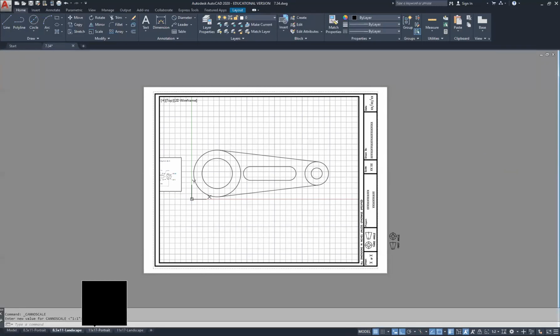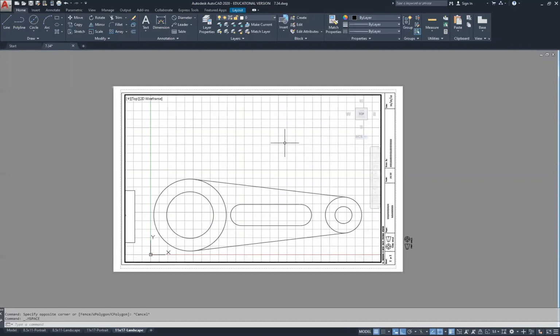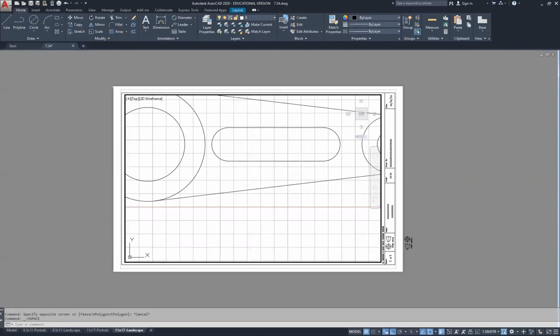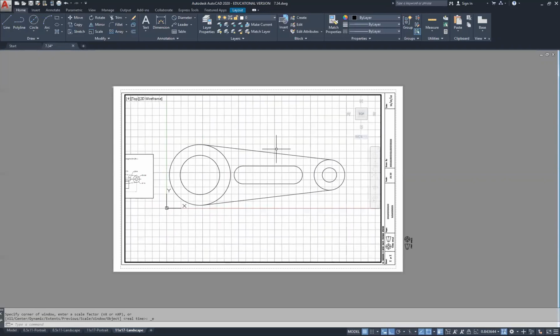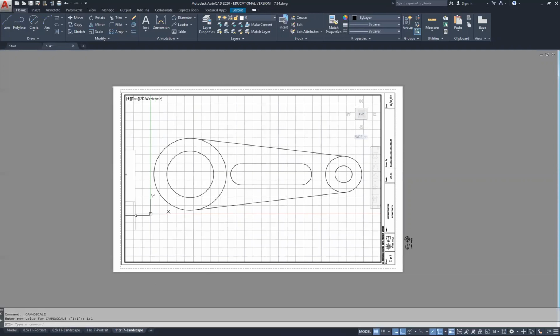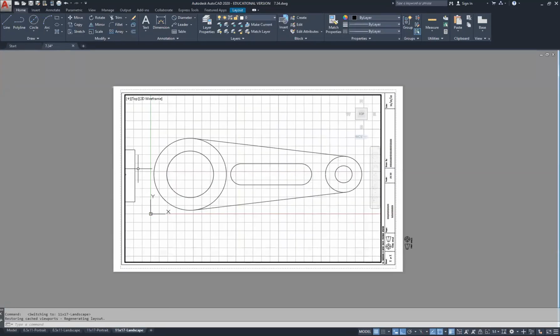We could also evaluate and see if we want to do an 11 by 17 in landscape. Double click inside the viewport, center it best we can. If you need to zoom in or zoom out, you can center scroll button twice to zoom all. I'll check the size and see at 1:1. This will fit on this sheet at 1:1 scale. Evaluating between the two sheets, what gives us the most room to work for dimensions and things of that nature.